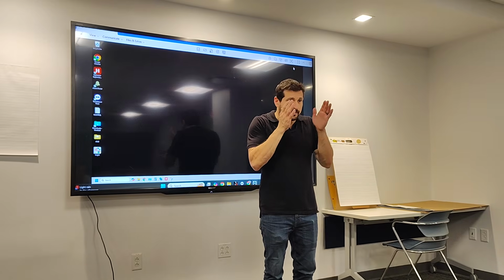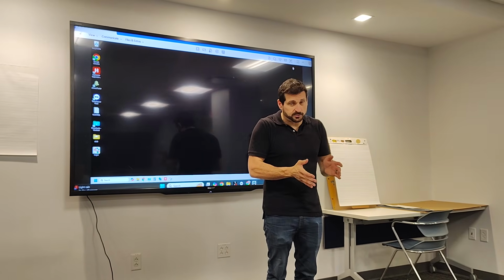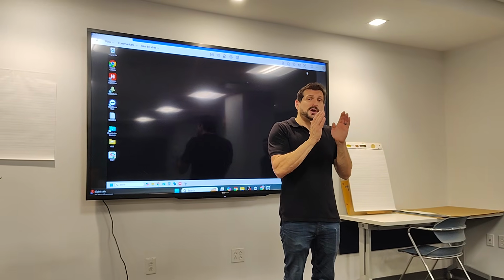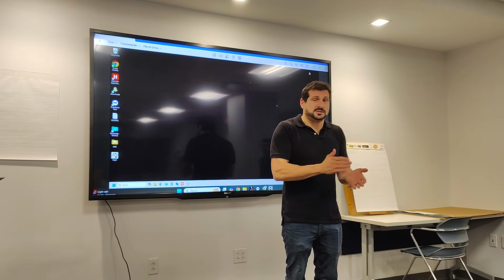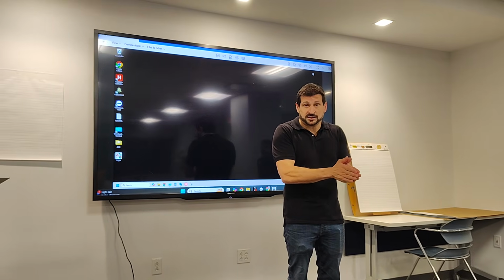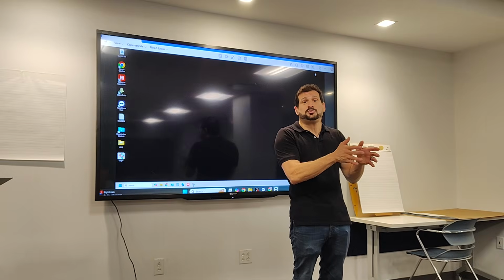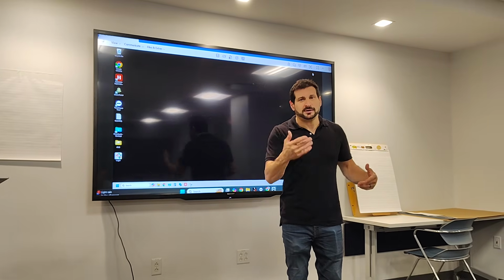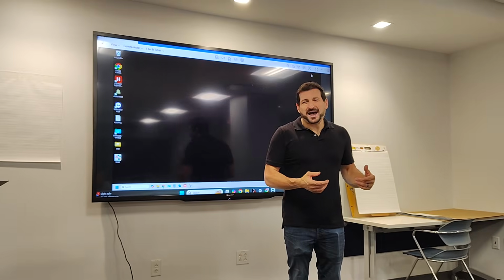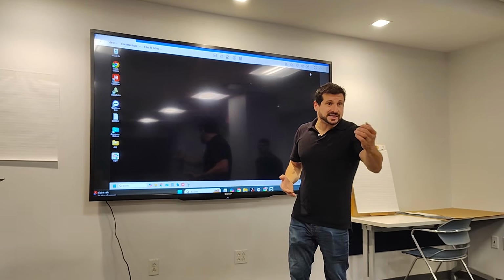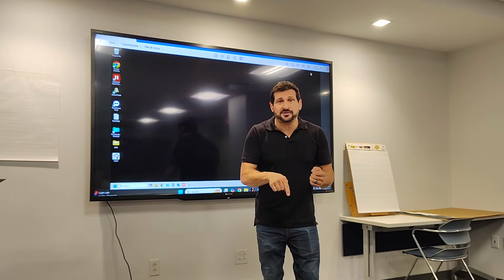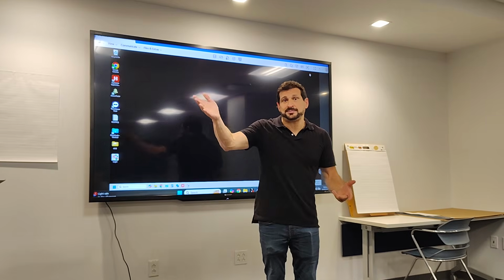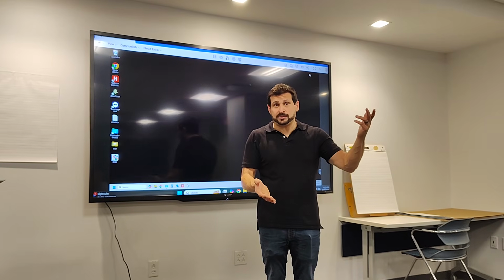The only points in a BMS that you want to adjust, if the programming is done properly, which we don't know about in this building, are the virtual points, the set points, occupancies, things like that, commands, right? The things that the BMS is being told to do. Inputs we don't touch. Outputs are for when I have an emergency. Sorry, shouldn't have cursed on your video. It's okay. Outputs are, I have an emergency. I have a leaking cooling tower. I need to force off my condenser water pump, or whatever I have to do, to stop that leaking cooling tower that's happening right now in the building, right?